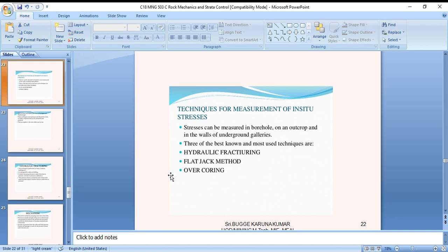The change in length measurement may range from less than 100 micro inches in borehole measurements to a number of feet in the case of surface subsidence. So deformation units are made on the surface of a solid body: change in length divided by the distance between the measuring points. The resulting average strain between these points is evidence that strain gauges are inherently deformation measuring devices. However, custom has established them as a separate class of instruments. They are treated accordingly in this book.